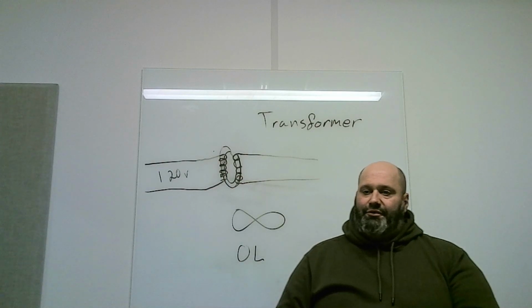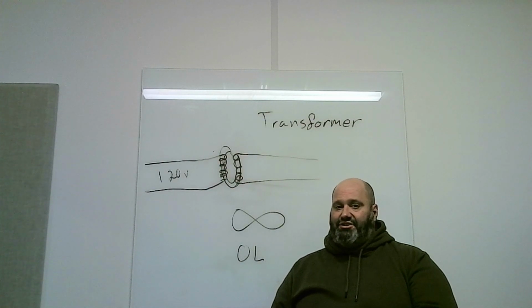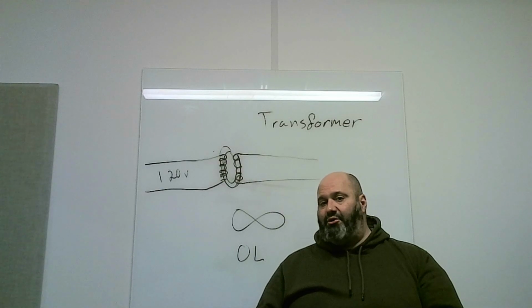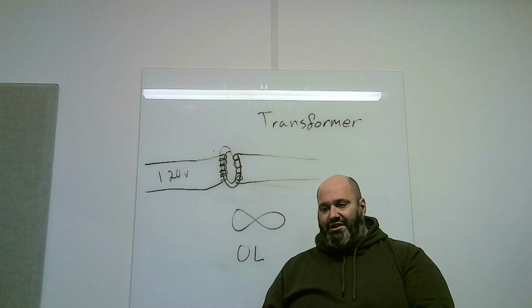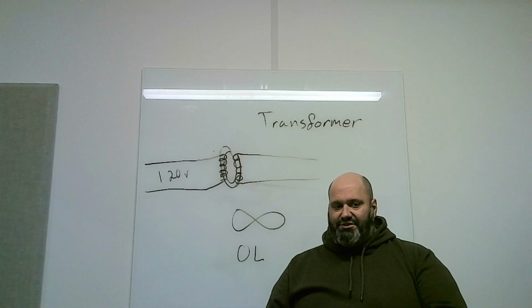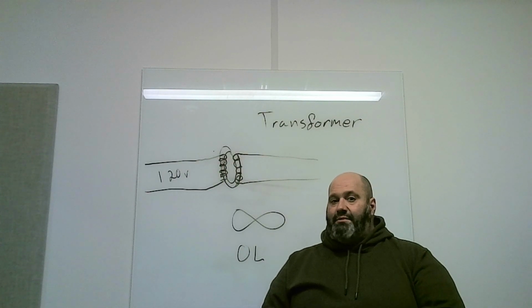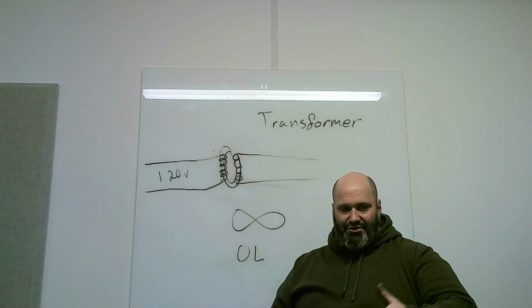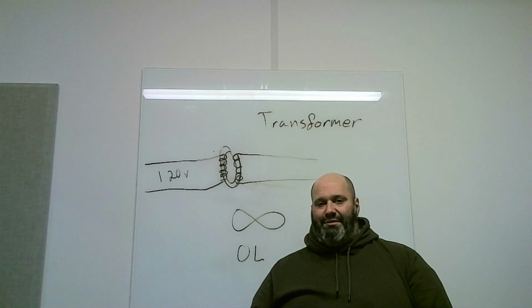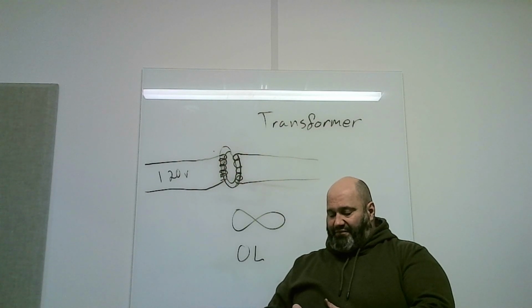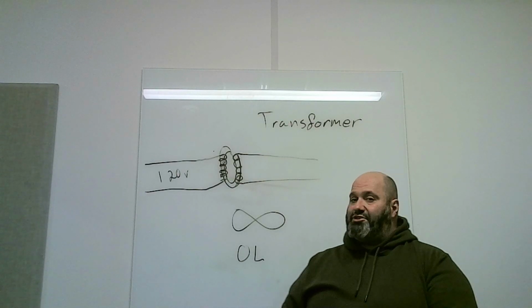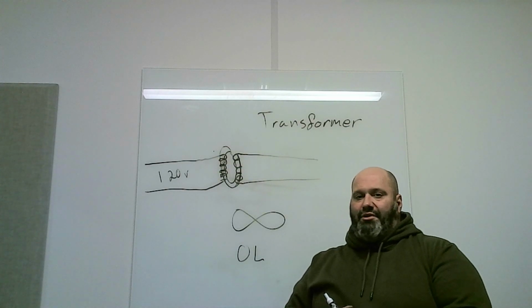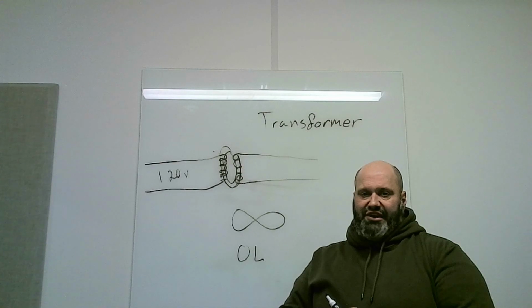The reason is that it's very easy to accidentally short the transformer, and now whatever component or part has brought you to this home that you are now checking, you now also have to replace the transformer. Been there, done that, guilty, and no doubt pretty much everyone who sees this video will have done the same at one point or another in their career. But that's just a short explanation of the transformer. It's pretty integral to, again, the operation of an HVAC system.